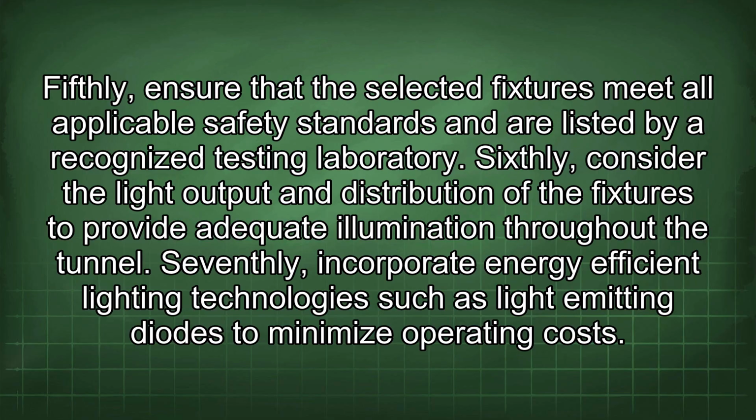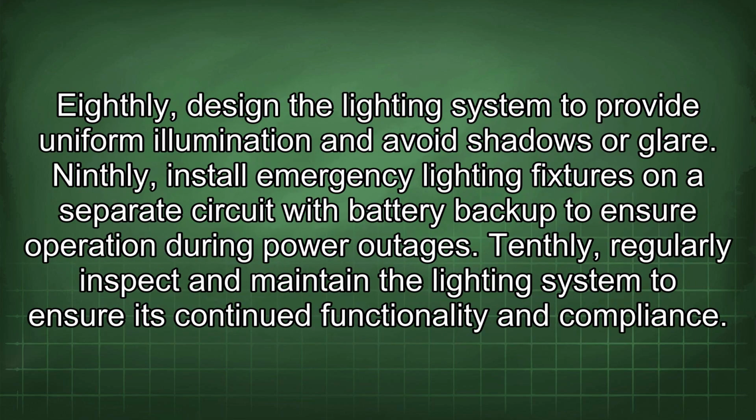Sixthly, consider the light output and distribution of the fixtures to provide adequate illumination throughout the tunnel. Seventhly, incorporate energy-efficient lighting technologies such as light-emitting diodes to minimize operating costs. Eighthly, design the lighting system to provide uniform illumination and avoid shadows or glare. Ninthly, install emergency lighting fixtures on a separate circuit with battery backup to ensure operation during power outages. Tenthly, regularly inspect and maintain the lighting system to ensure its continued functionality and compliance.